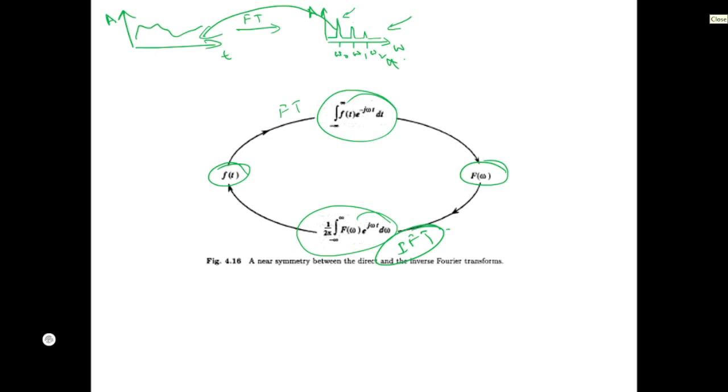By transforming the signal into the frequency domain, we can see whether the 60 hertz signal is present in the original signal, and if it is, we apply a band stop filter to suppress it. Or suppose there is a 100 hertz frequency component and we want to gather just that component, then we use a band pass filter to extract that particular frequency component.